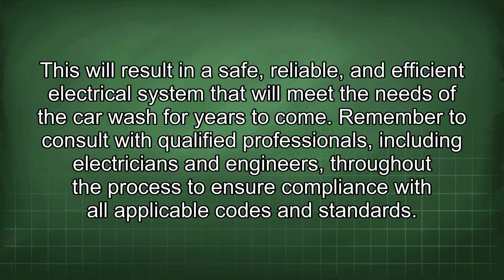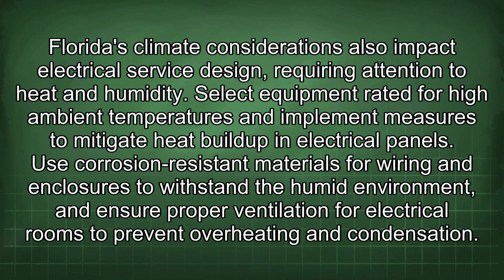Florida's climate considerations also impact electrical service design, requiring attention to heat and humidity. Select equipment rated for high ambient temperatures and implement measures to mitigate heat buildup in electrical panels. Use corrosion-resistant materials for wiring and enclosures to withstand the humid environment, and ensure proper ventilation for electrical rooms to prevent overheating and condensation.